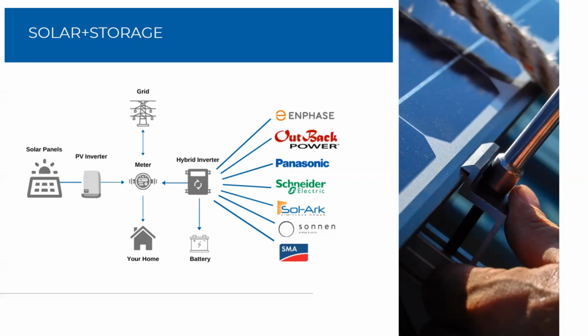Whenever I'm talking to installers and we're talking about a retrofit, the first question I ask is, what's the size of the PV inverter? Because if we say we have a 5 kilowatt inverter, great. I can choose from any output that is rated to 5 kilowatts or less. If I have a 10 kilowatt inverter, we have to adapt our options based on that size. Then the second question that I typically ask is, how much of the PV do you want to remain on in the event of an outage? Because we want to know how much of your house you want to power.